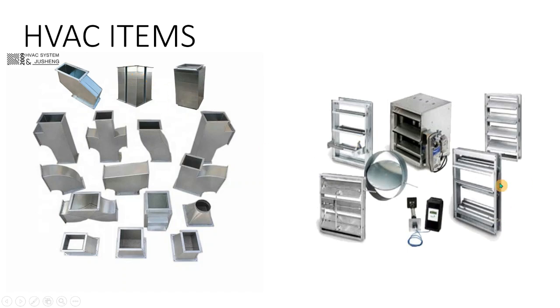And these are all the dampers. As you can see, we will use the damper for balancing, then shut off purposes for the HVAC duct system. We have sensors as well, as you can see in this picture. So this will be helpful if you want to measure the duct static pressure or the airflow inside the duct. You can install these sensors as well, depending on the requirement, depending on the detail that they have mentioned in the drawing.